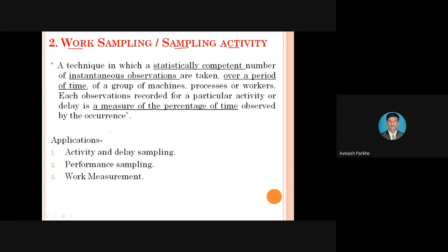In case of a time study, we are measuring with time study equipment. Maybe we are using the stopwatch, the time study board, the time study sheet. That means we note detailed readings in a time study. But in work sampling, we are not measuring actual readings using the stopwatch, the time study board or the time study sheet. Only the supervisor or top management visits that particular production department a number of times in one day, and from those visits he identifies the percentage of working condition and the percentage of idle condition.